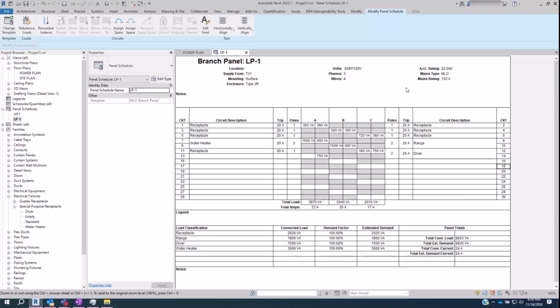There's times when you use a 100% rated breaker, and I'm pretty sure we've talked about that in previous videos. But for something in the middle of nowhere where you're not even close, don't spend the extra money. Use an 80% rated breaker and be done with it. So we don't want a total of any more than 80 amps on this panel board, because there's a high probability that all of these receptacles, the range, the dryer, the water heater will all be running at the same time.